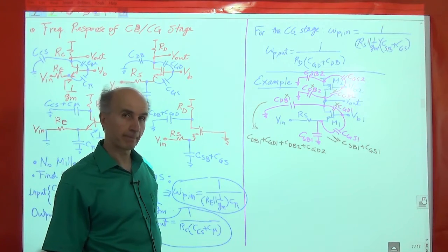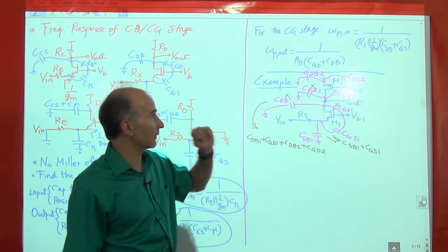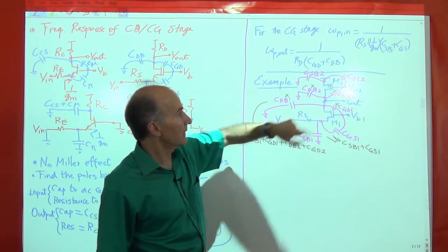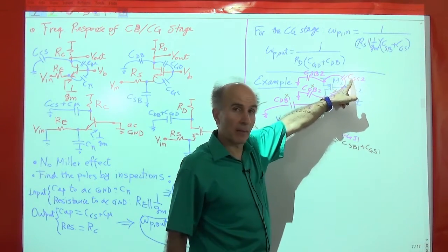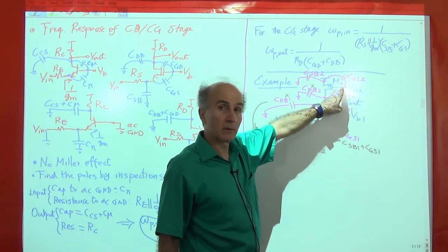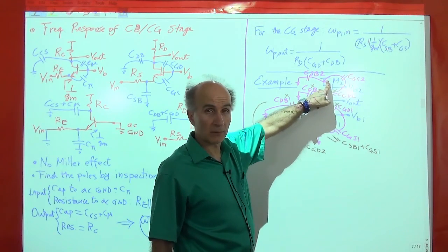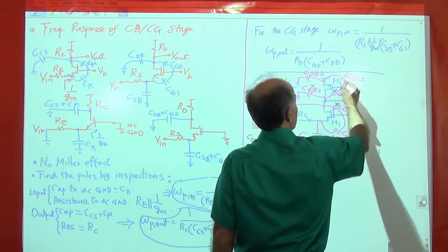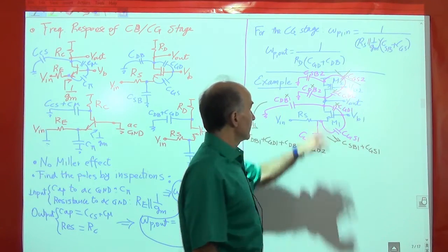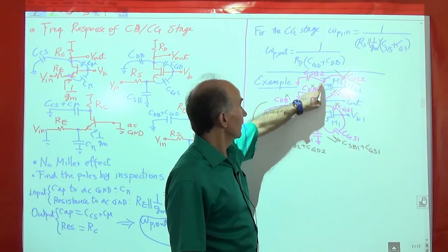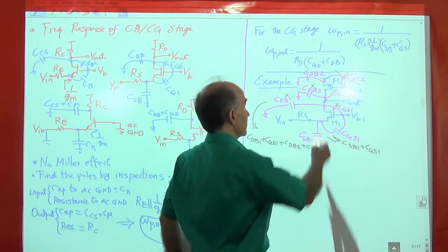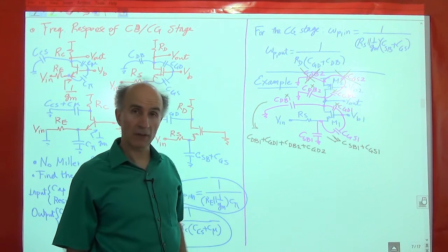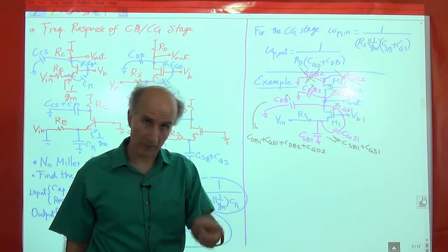All right. Okay, so we got two more capacitors left, this guy and this guy. So what do we do with these? CGS2 goes from AC ground to VDD, AC ground. So it doesn't do anything, right? It's shorted out. So that's gone. And then CSB2 goes from AC ground to AC ground. So that's also gone. So that's very nice, right? So the circuit suddenly becomes much simpler.